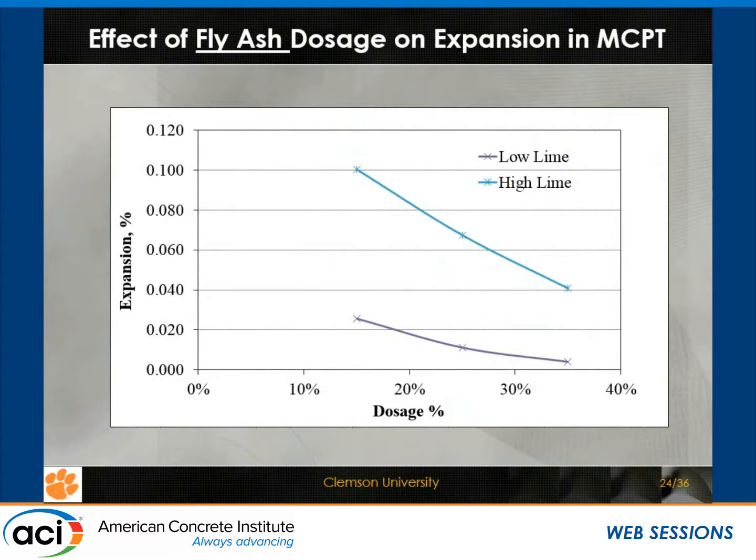And again, with fly ashes, clearly the low lime or the class F ashes versus class C ashes, there's a big difference in terms of the dosage level and how it influences. So again, all these need to be captured in the job mix.